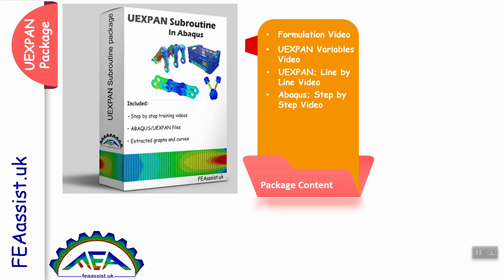Every UEXPAN subroutine needs to be solved by Abaqus solver. So the Abaqus model is also explained step by step in the videos. At the end, result extraction is explained in separate videos. All Abaqus and UEXPAN files are also included in this package.